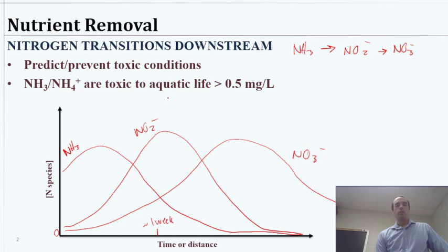And here I have a note that ammonia, anything above 0.5 milligrams per liter, is toxic. So if you just had the fish there and none of this stuff was happening and it just delayed for a very long time, you might just be increasing ammonia for quite some time before it significantly starts to be removed.